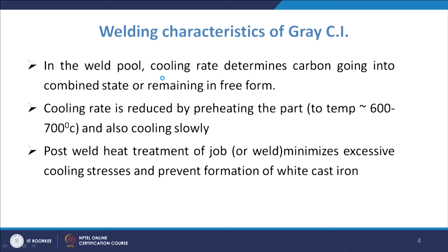So, it will make Fe3C, and the whole purpose of making the gray cast iron is lost, and that is what normally happens in welding. In welding, the heating and cooling rate is higher, so it is very difficult to form graphite under higher cooling rate conditions.